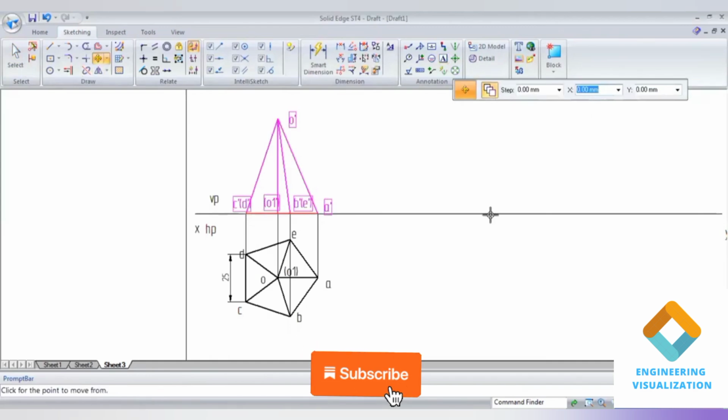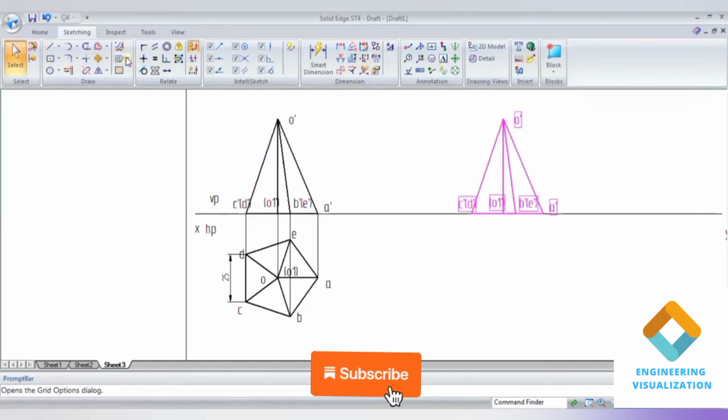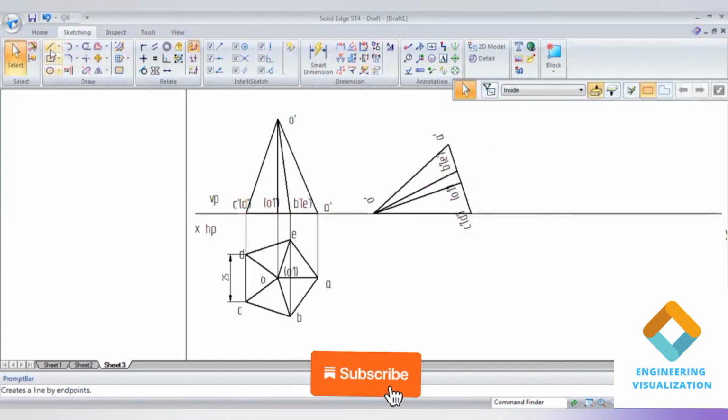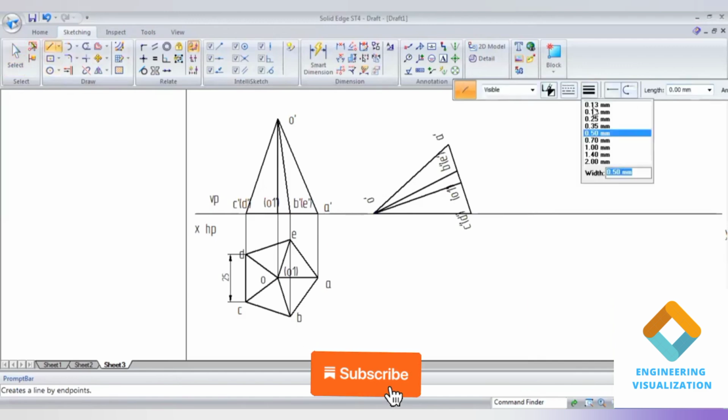Okay, copy this and using a move command, slide along the XY line, and then select these heads. However it is there in the solution book, I'm following the same procedure here. Now project downward to complete the second position top view here.